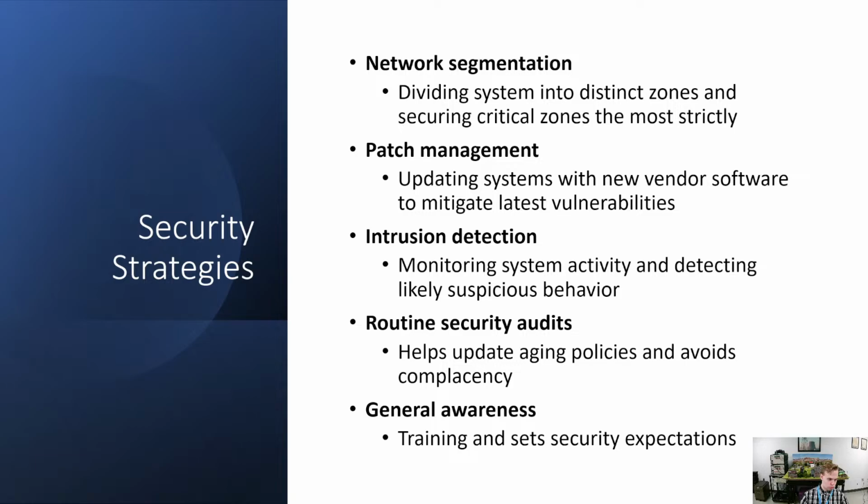You also want some type of intrusion detection, so just monitoring system activity, say with your data historian, and being able to detect likely suspicious behavior. So if you see some suspicious behavior, say it looks like there may be some false data coming from one of your PLCs, you might want to look into that and not just assume, oh, it's a glitch or something's wrong. You shouldn't just not worry about it.